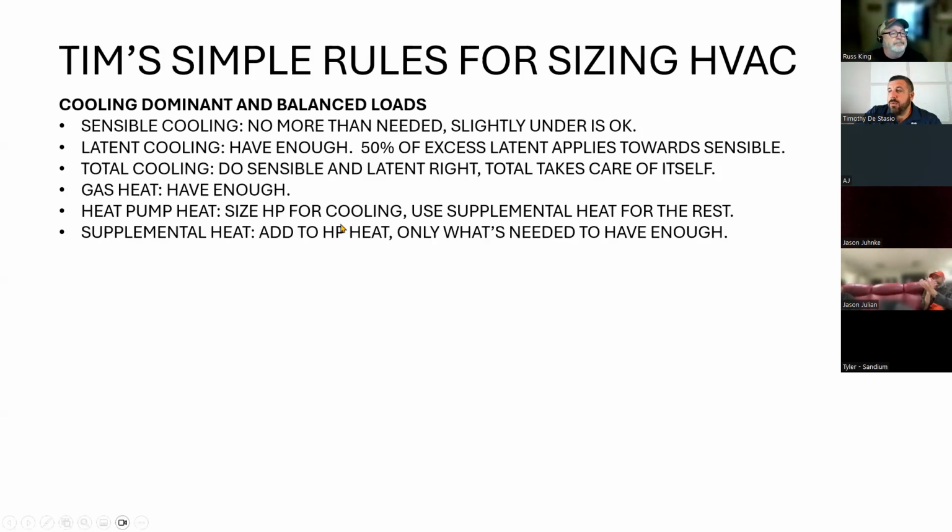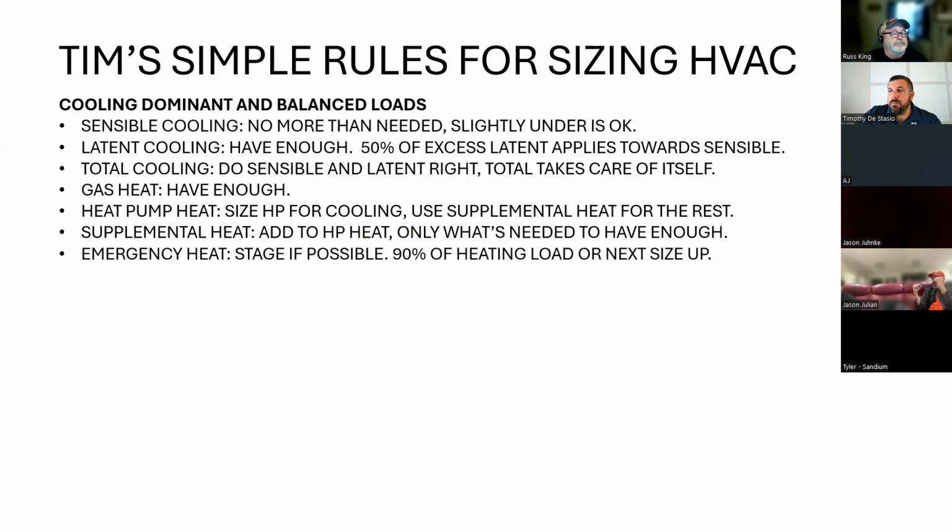Supplemental heat, we just add that to the heat pump heat. We only need what's needed so that we can have enough heat. We don't need to overdo our supplemental heat. But emergency heat, if it's a different heat strip, then stage it if possible.